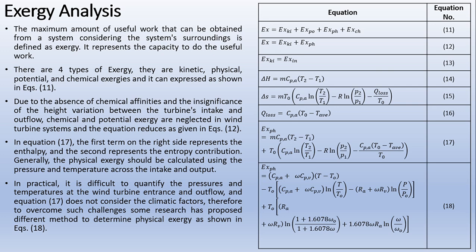The potential and the chemical exergy are ignored due to the absence of the chemical affinity and the insignificance of the height variation between the turbine intake and the outflow. In this project, we will only consider the kinetic exergy and the physical exergy.